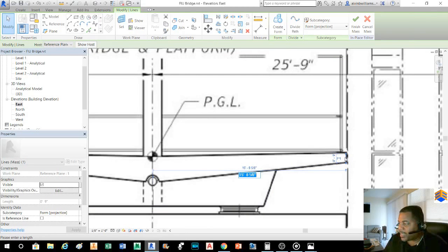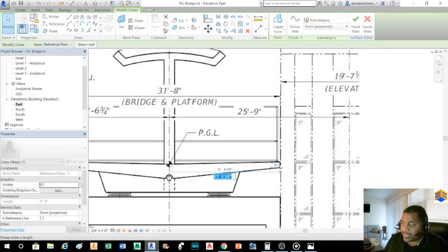And you start off by clicking the actual line that you want to move. I apologize, I didn't say that earlier. You want to click on the line that you want to move first. Click on that line, or double click on that line. In this mode, you're going to double click the line, because if you only click once, you're actually highlighting the entire segment that you saw me draw in here earlier.